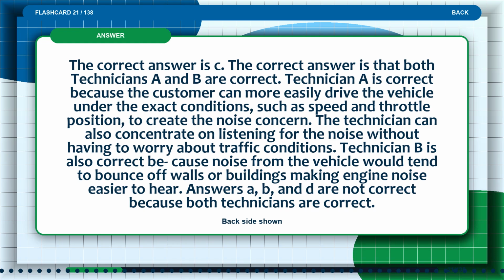The correct answer is C. The correct answer is that both technicians A and B are correct. Technician A is correct because the customer can more easily drive the vehicle under the exact conditions, such as speed and throttle position, to create the noise concern. The technician can also concentrate on listening for the noise without having to worry about traffic conditions. Technician B is also correct because noise from the vehicle would tend to bounce off walls or buildings, making engine noise easier to hear. Answers A, B, and D are not correct because both technicians are correct.